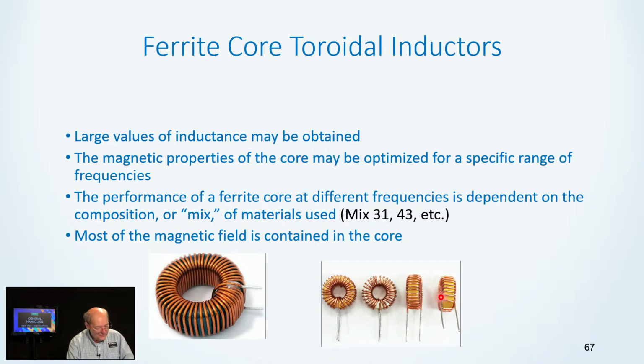Oh, finally, some things we will need to know. So ferrite core toroidal inductors. The ferrite core is here. It's usually a ceramic material with a certain amount of ferric material, powdered iron, for example, and then the wire is wound around it. So the toroid, that means it's round like this, or donut. They're donut shaped, and you can recognize them instantly. Most modern transceivers are using toroidal inductors for reasons that we'll mention.